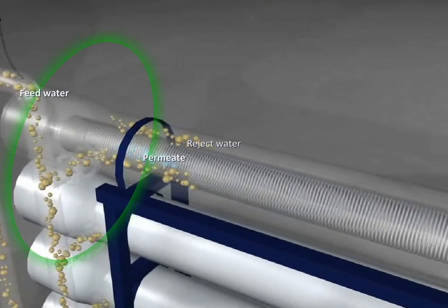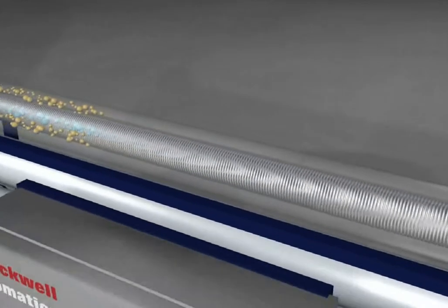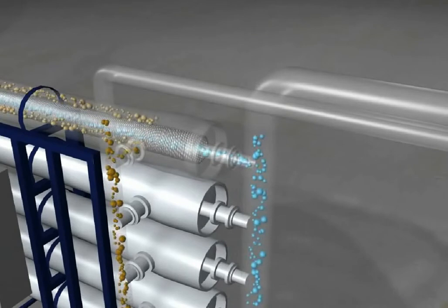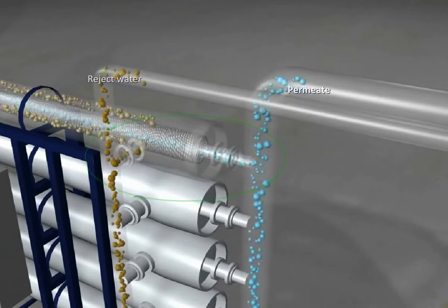The RO supply header distributes flow to each of the 5 RO pressure vessels. The pressure vessels have 2 flow paths which exit the other side of the vessel. Flow that has passed through the RO membrane is collected through a tube located in the center of the pressure vessel. This water is called permeate due to the fact that it is permeated or passed through the membrane. Permeate is collected from all of the pressure vessels. Concentrate is the fluid containing the contaminants that are rejected by the filter. This concentrate is directed to the reject water tank, where it can then be transferred.